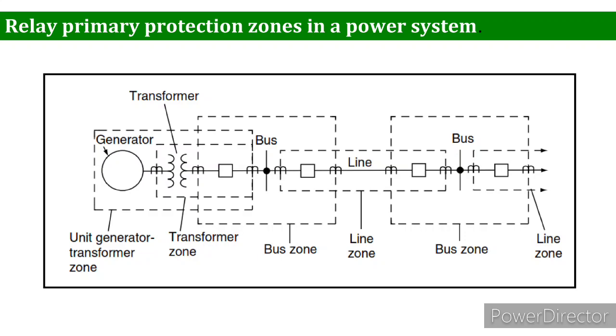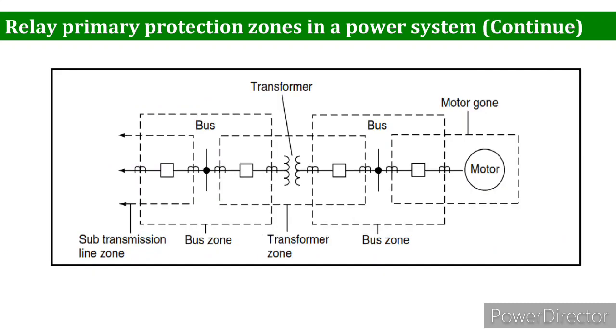Each has protective relays specifically designed for protection that are based on the characteristic of the equipment being protected. The protection of each zone normally includes relays that can provide backup for the relays protecting the adjacent equipment. The protection in each zone should overlap in that adjacent zone.